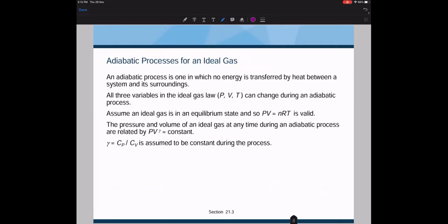Now, of course, if you are trying to heat up the gas, you expect a change in temperature. So that is why we are not discussing a constant temperature process. When you have a constant temperature process, delta T is 0, so internal energy change is 0. That is the idea. But what about an adiabatic process?